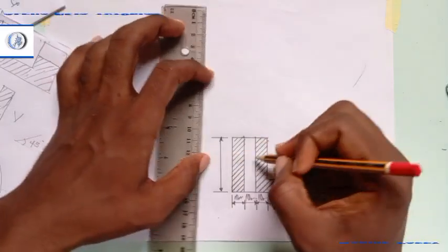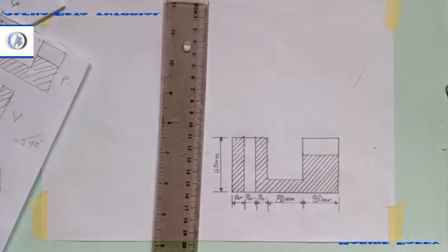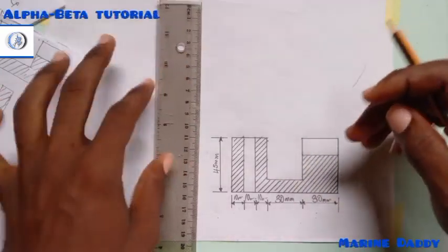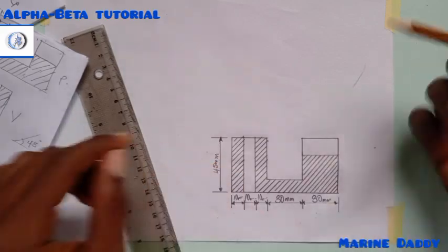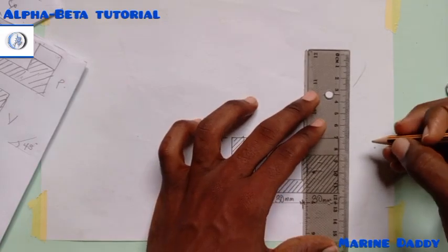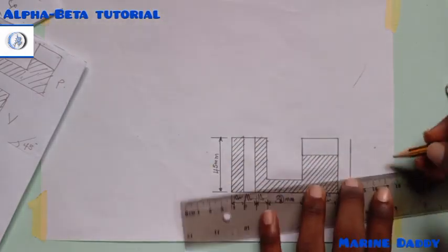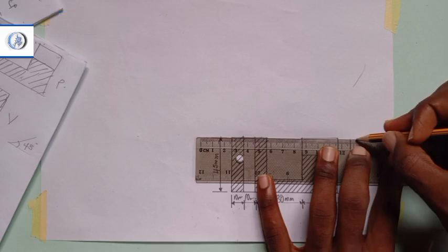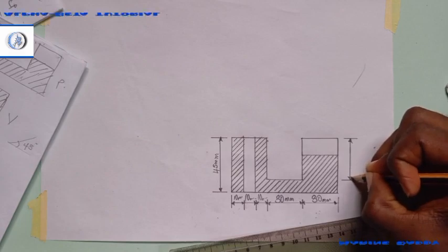distance. So here to here is how many? I think it's 45 millimeter. And if you are using your dimension, make sure that everything should be in the same unit. This one now I don't say use centimeter. Sometimes you use centimeter for the smaller part and use meter for the bigger part. I don't know who taught you that one. So you can come to this side, measure only. Okay, you can come here to here, do your measurement from here to here.